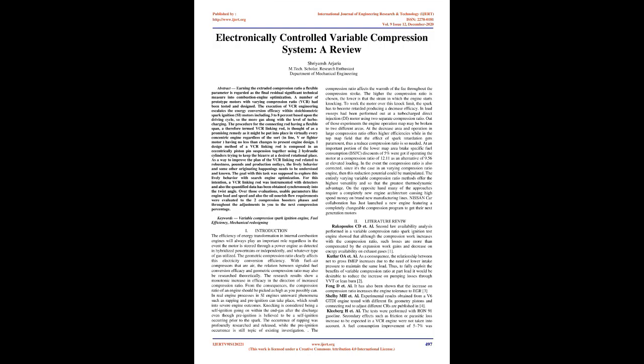Electronically controlled variable compression. Abstract: The compression ratio, a flexible parameter, is regarded as the final residual significant technical measure in combustion engine optimization. A number of prototype engines with variable compression ratio, VCR, have been tested and designed. The implementation of VCR technology increases the energy conversion efficiency within stoichiometric spark ignition, SI, engines, by 3 to 8%